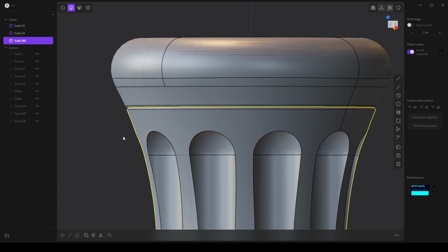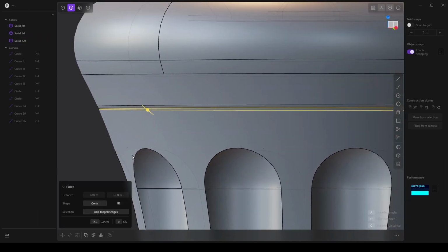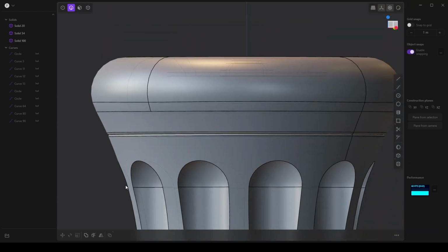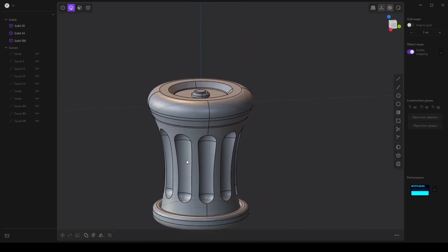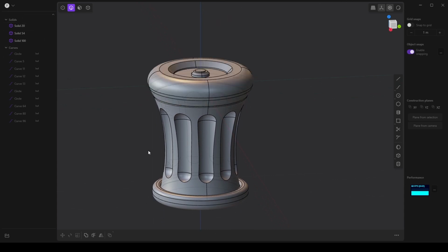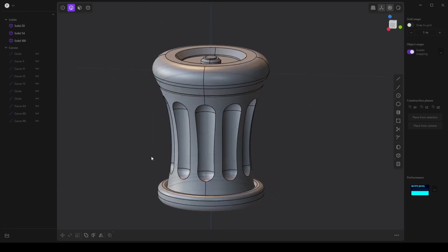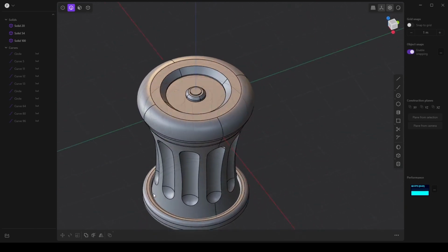And whoop, let's see, it looks like that did a chamfer when I want to fillet. I'm not exactly sure how to pronounce it. Press D. Perfect. So what this will allow us to do is keep these two pieces separate, and it just adds more visual interest for the final result.